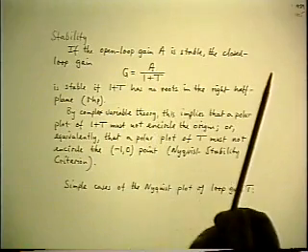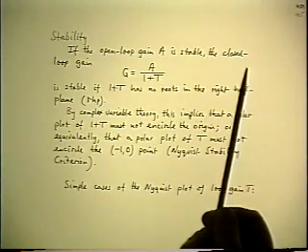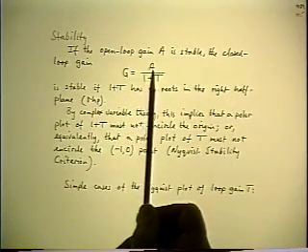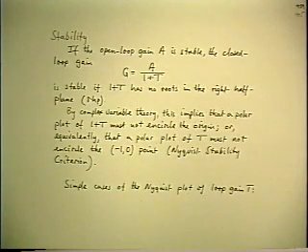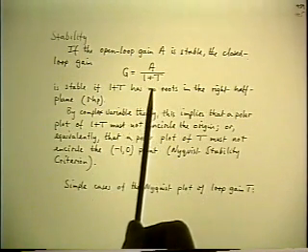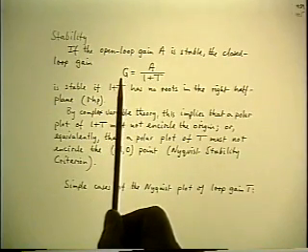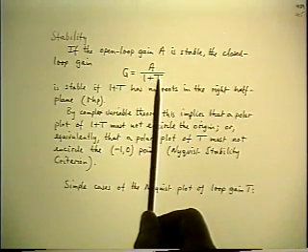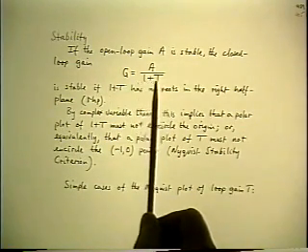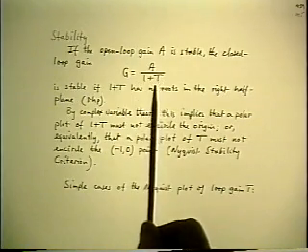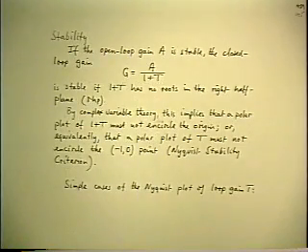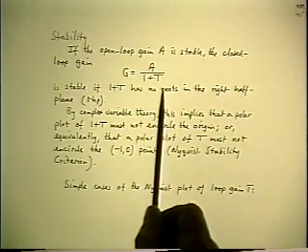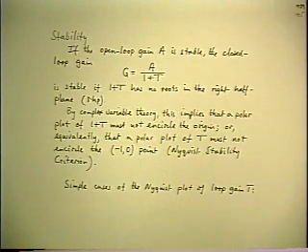So, the zeros of A don't matter, whether they're right or left half plane. So if we impose the condition that A itself has only left half plane poles, then we can dispose of A from further consideration. And the only thing left that determines the stability of the closed loop feedback amplifier is the zeros of F. F is 1 plus T. F is in the denominator, so the zeros of F are the poles of G. So the stability requirement is that the roots of F, which are at zeros, should all be in the left half of the complex plane.